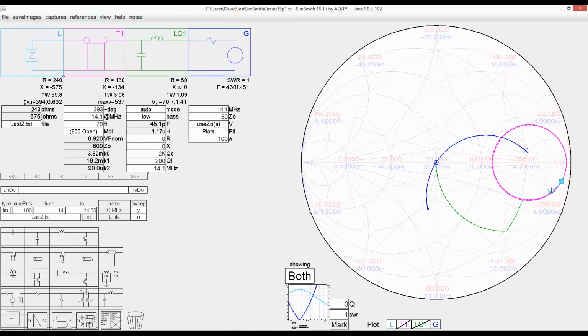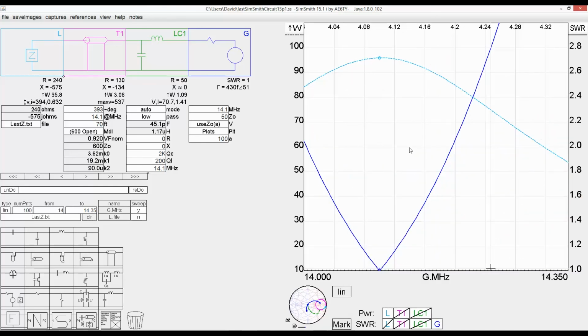Here again, I'm looking at the Smith chart. Here again on the right, we see our original sweep. But look how tight this is. That's the same length. It's gone around several times. You can see that as it has spiraled in, there's not much loss. It kind of stays right on top of itself. We end up here. That's the end, and then the L network transforms it the rest of the way to 50 ohms.